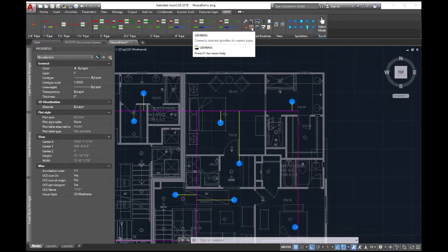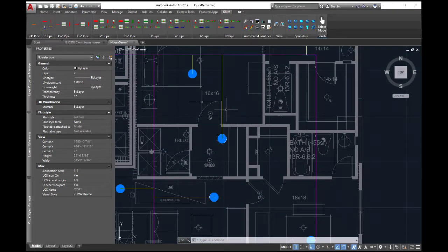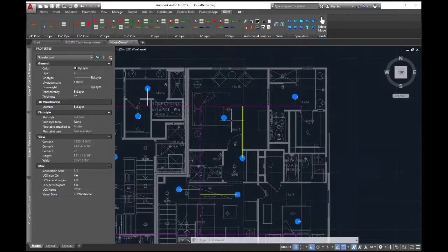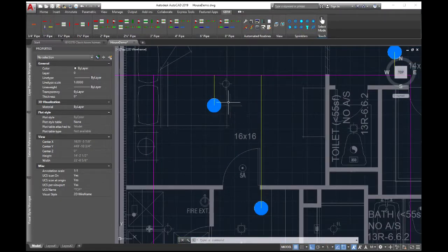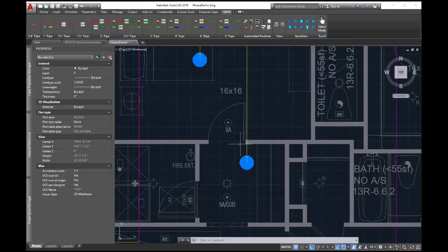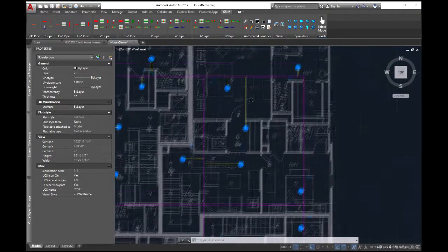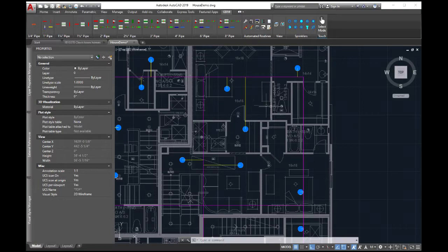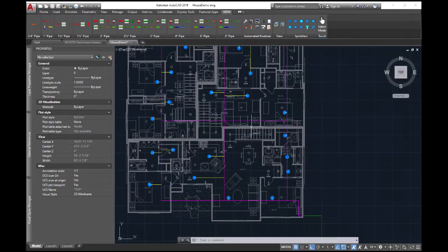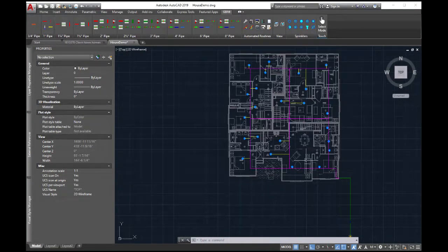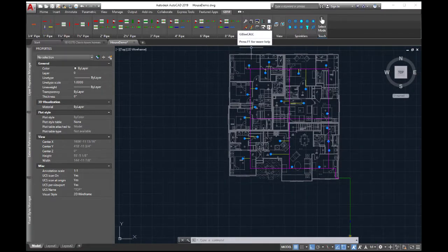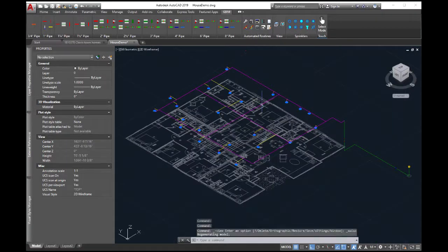That's automatic sprinkler connection. It will not stretch too far, because the logic of the way that works is that this head starts searching for a piece of pipe, and it stretches out a little farther, a little farther, a little farther. After it gets to be about 6 feet or so, it just stops looking. It decides it's not close enough to anything. So these look like they might all be connected. So let's take an ISO look.